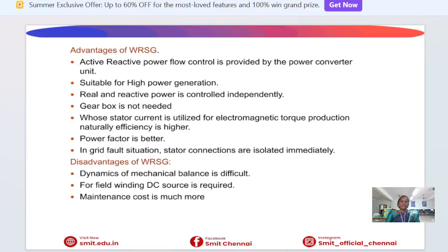However, WRSG also has some disadvantages. It requires a DC excitation source for the rotor field winding. Mechanical balancing is more complex and maintenance costs are high compared to simpler generator types.